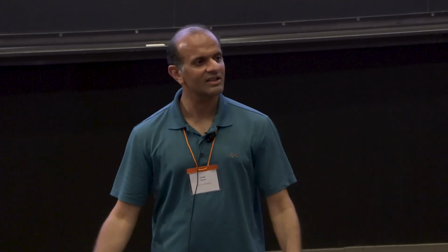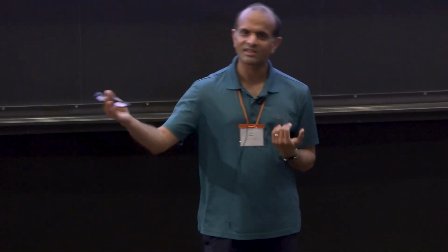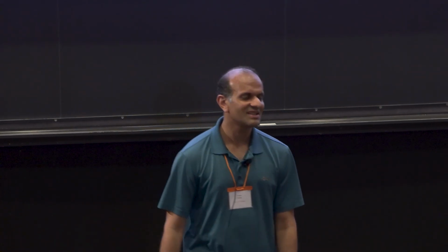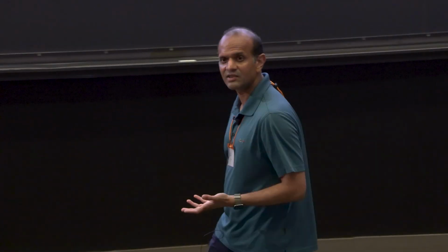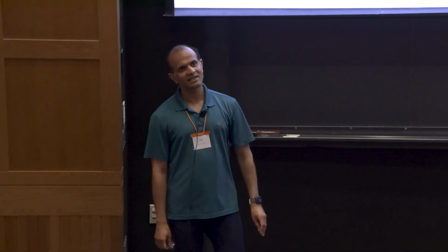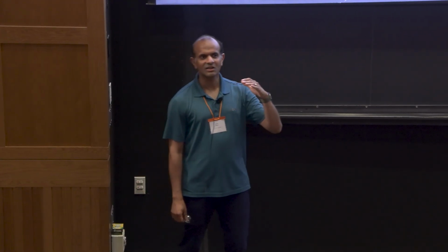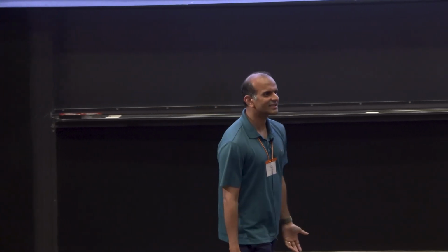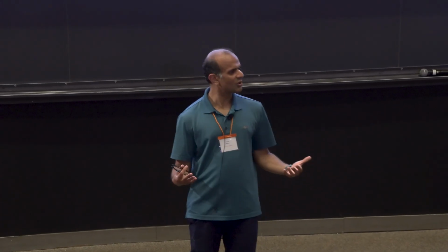Because there are coefficients in RANS that you can tune whichever way you want, and you'll get any result. Flow will be turbulent, laminar, it will transition, flames will burn, extinguish, everything in one simulation. That was the problem. And the promise of LES is that you do not have to go through that extensive modeling. Somehow, because you're only modeling the small scales, and somehow they're not important, which we said is also not true for combustion. But let's say it's not important, it's better. But this equation does not give you that. It tells you nothing new than what you had originally, except that now you have the ability to solve it in a coarse way. That's about it.